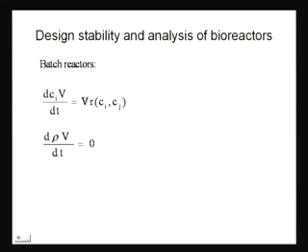Okay. So this is a total volume balance. This is a balance for the particular component Ci, and this is the total volume balance, rho being the density. For a constant volume, constant density system, this whole term would be 0, and you can take V out of the system. So this is for liquid reactions or constant volume, constant density systems. You can take it out of the differential, and you can write dC/dt equals r of C, right.